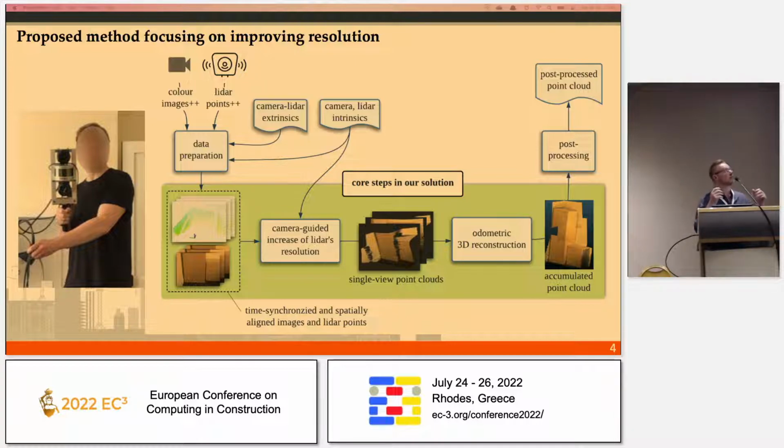The point here is to synchronize them in time, and I do that through standard techniques in robotics, where each message is time-stamped, and if the difference in timestamp is smaller than a certain threshold, then I consider such messages to be time-synchronized. In addition, we need to spatially register images and LiDAR scans so that they give me a geometry-consistent signal.